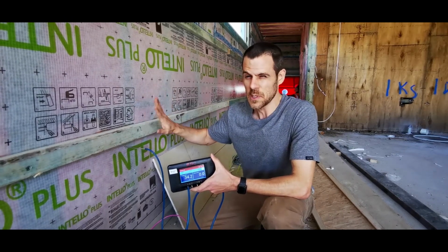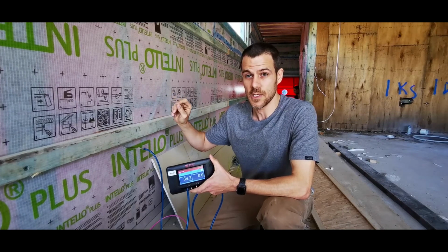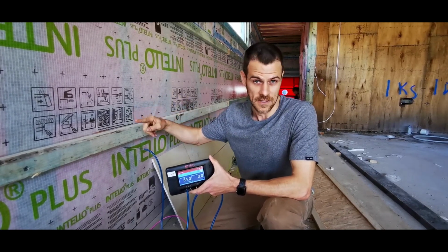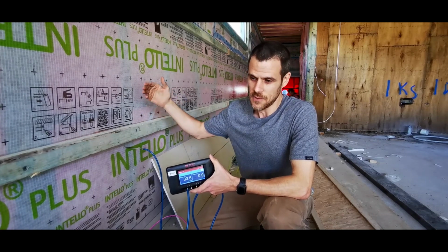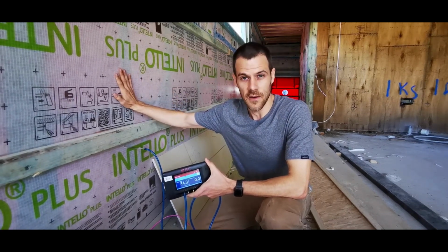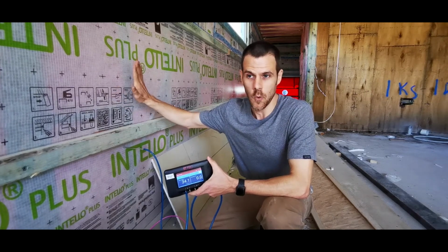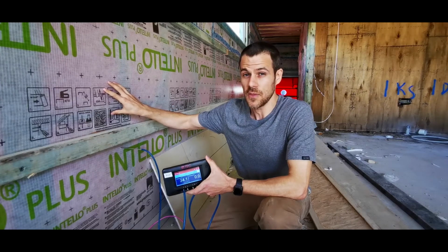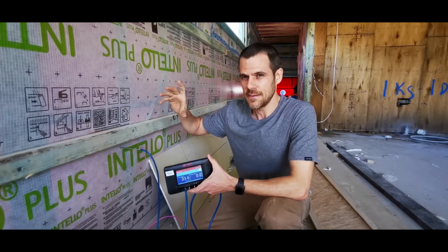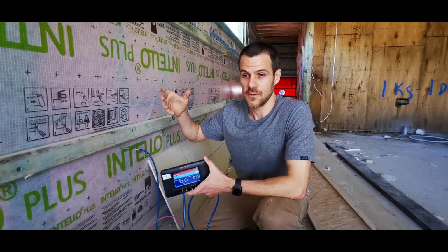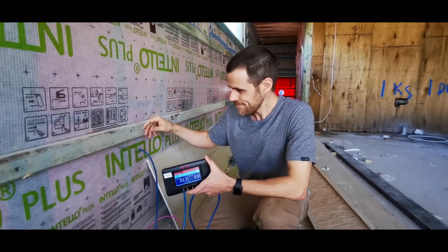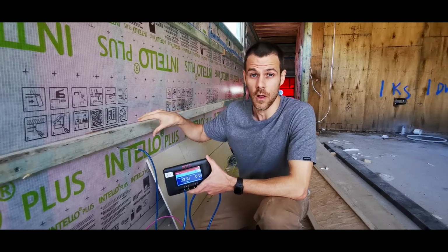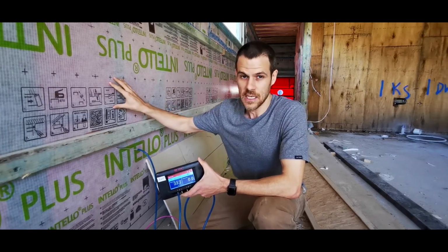It's almost like you can draw diagrams like this, almost like electrical resistance. If the whole voltage across the whole thing is 50 pascals, well, there's a resistor with the exterior WRB of 17 ohms, or 17 pascals, and then a resistance here of another 33 pascals. And then you say, which resistor is the weaker resistor? The exterior WRB in this building, at least on this wall, is doing less than the interior air barrier.